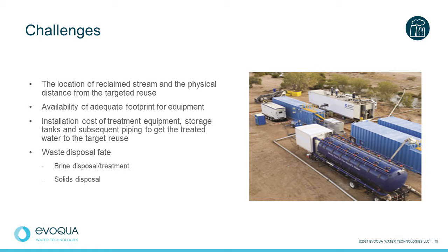For example, localized capture, point source treatment and reuse of a small volume stream within an operating unit can still be cost effective despite higher unit volume treatment costs. The competing cost of piping in an alternate water supply inside an existing facility can be high, and thus compares favorably to a more remote tailpipe project.